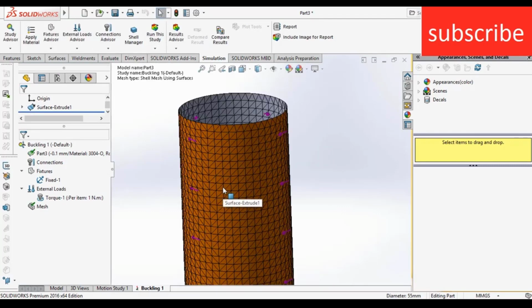Now as you can see, when I click on fine mesh, it creates the mesh very quickly and accurately. That is the advantage of shell manager. Now right click on run the study.